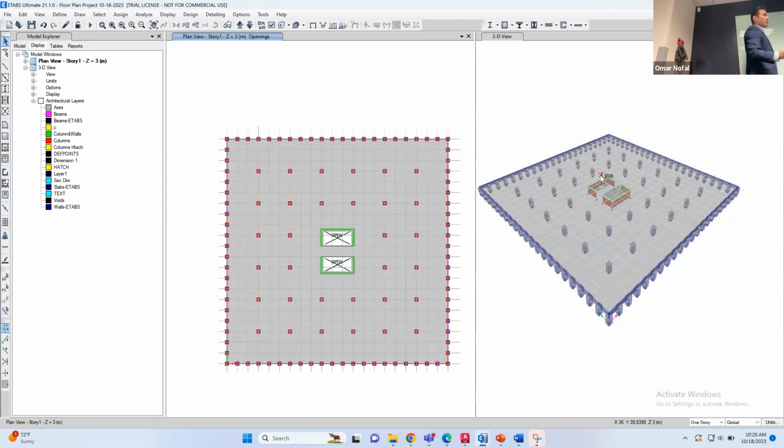And as we talked last time, if this is one shear wall, like this, that doesn't have any openings, like this is an opening, and you have a load here and make a moment like this, the stress curve is going to be tension here, compression here, and the stress-strain is going to be something like this. This is how the moment is going to develop, like you will have a force here and a force here, and this is how the moment looks.